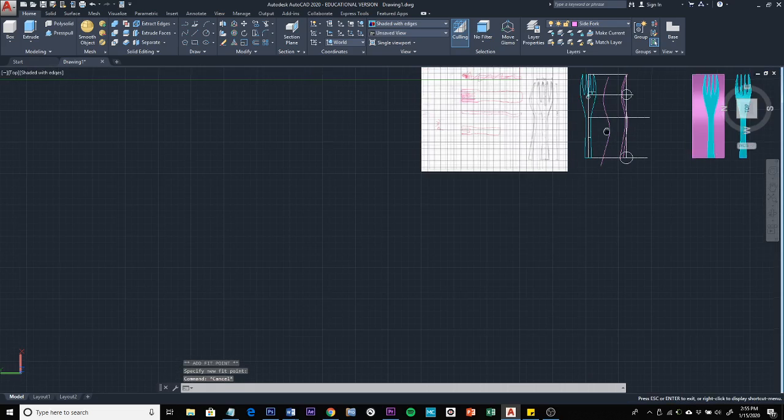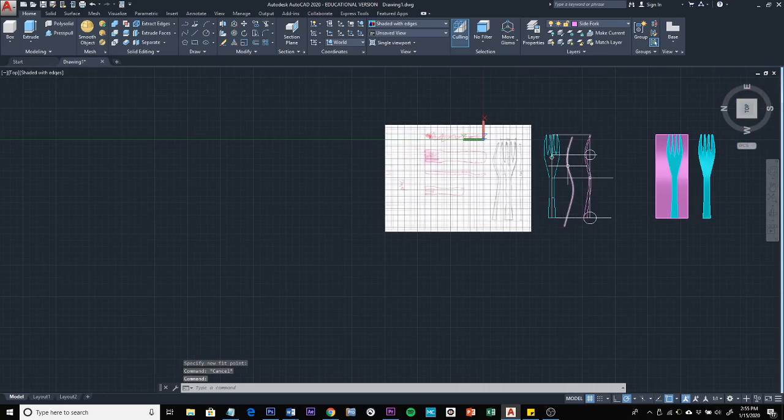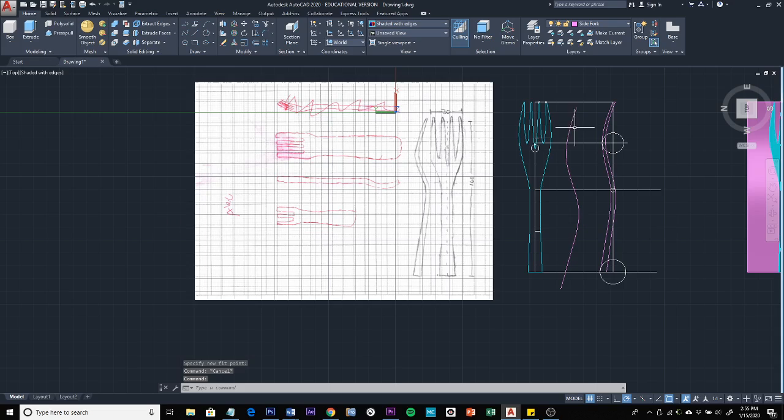So when you're creating your splines, a lot of times the first time you make it, it's not perfect. So you need to either add some fit points or adjust fit points to make it look the way you want it to. Okay, so from your top view and your side view, once you get those modeled in 2 dimensions with just lines and they're all joined together, so this is all one spline and this is all one spline, then you're ready to extrude them.